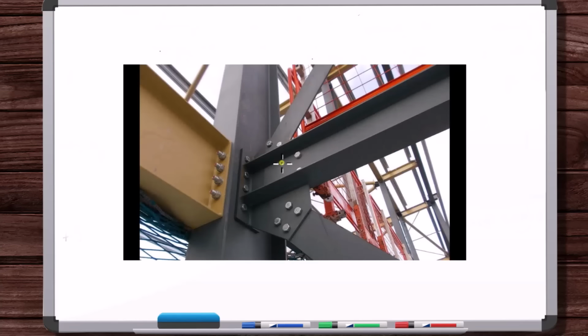So for this beam here, it looks like these pieces are welded to the beam. I could remove this beam fictitiously, like bring it into empty space. It's bolted here to this vertical beam, and then it's bolted at these plates that are welded to these angled beams. I could remove those connection points. And then, as we talked about, those are points where this beam was contacting something in its environment. So those are contact points, and so I put forces there. We talked about this before, but we're going to get into this in a second.